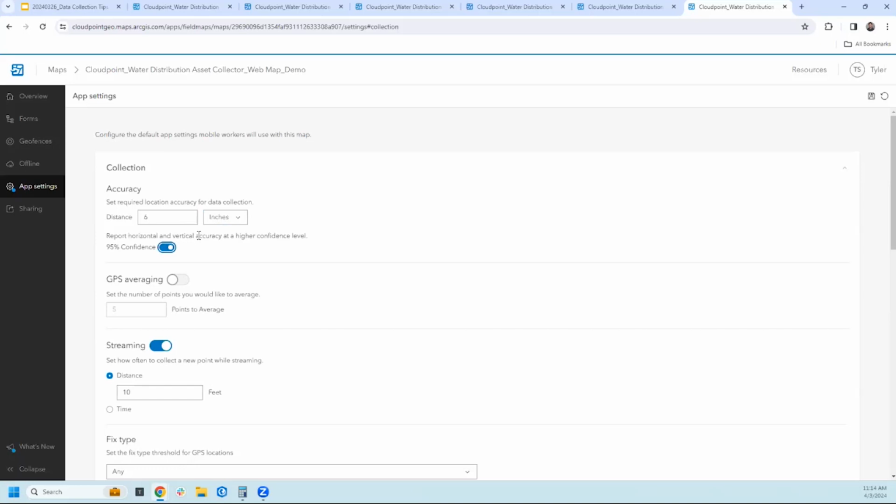It allows you to not have to be so focused on whether your signal is going to jump up and your accuracy is going to get thrown off. It will pause your averaging, and then it will automatically resume once your signal gets better.